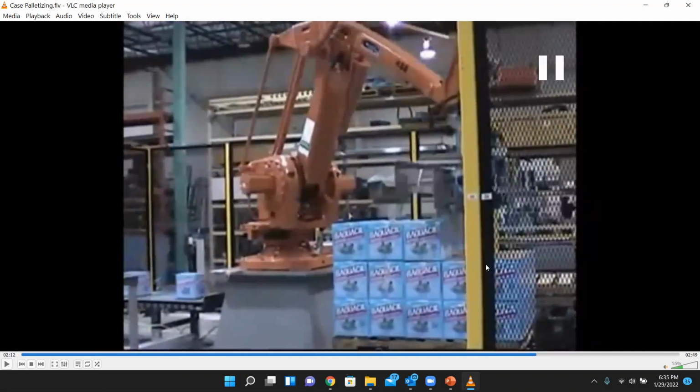Right. So every 2 layers of these items, you put another board, because you cannot have these continuous vertical lines of boxes, because they will fall apart very easily if you do that. This board, after 2 layers, or every layer, if you put a board, it means you discontinue